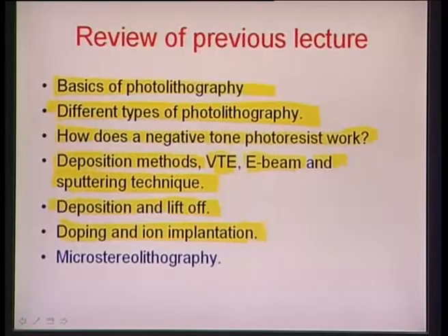You basically prepare a hydride gas or some kind of a gaseous state of the particular species that you want to implant, and then you ionize this gas and accelerate the ions, like boron or arsenic or gallium, through long tubes and perforated anodes and perforated cathodes respectively. The acceleration goes on building up, and then a central magnetic field is applied to divert these ions and separate them on the basis of their mass. If the field is constant, they would all move at different accelerations depending on their charge per unit mass ratio.